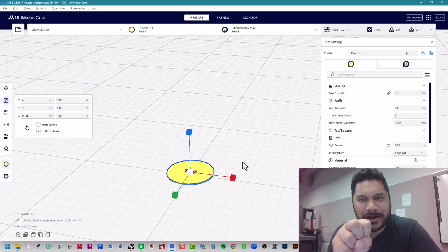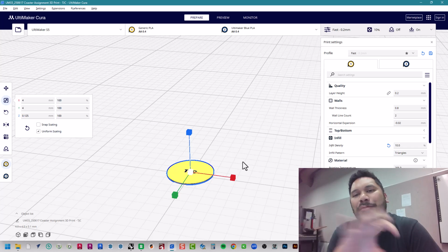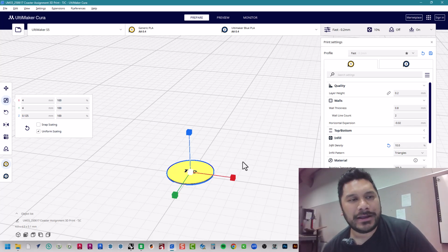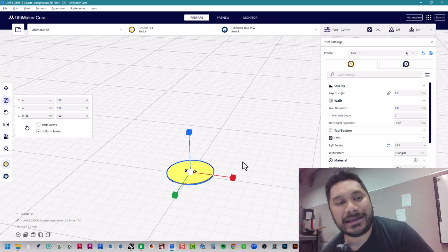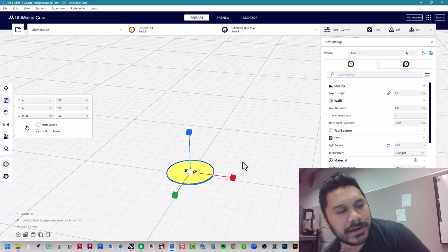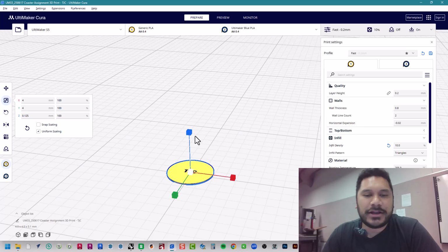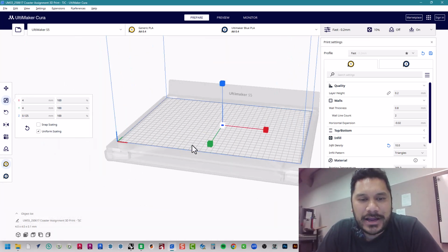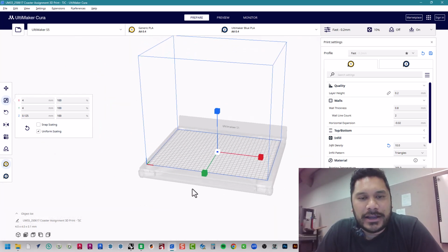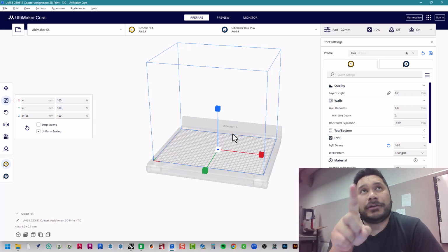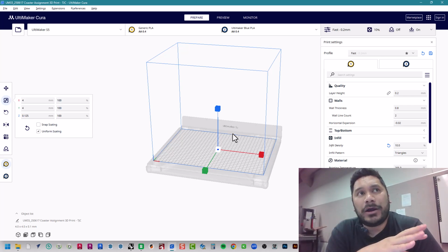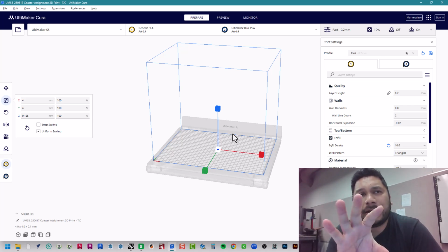However, another process that you can do is, if you don't want to touch that, then you can just scale it up. Oh, also, if you go that route where you're in Rhino and you 3D model it in Imperial, and then you switch quickly to metric to export it, after you've made that export, you can undo as far as you can to go back to Imperial. So that way you don't change your file, you're not stuck in millimeters all the time. Okay, so now what we want to do is we want to scale this up.